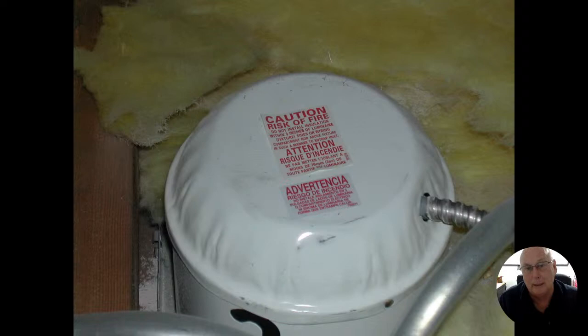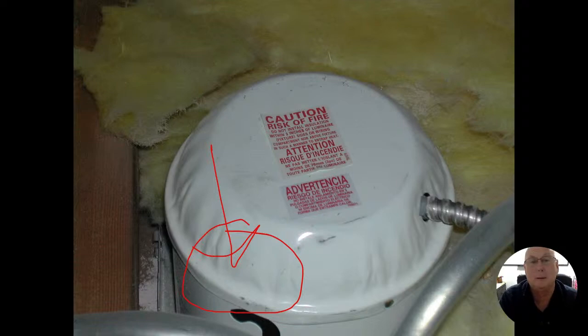If you have these can lights up in an attic or an unconditioned space, you're going to have a tremendous amount of heat loss coming up through there, because this opening down here at the bottom, I couldn't get down there, sorry, that opening at the bottom is clear through. You'll actually see light shining through there. Same thing where this pipe comes through. Once those bulbs start getting hot, heat just goes up into the attic. And once we start heating our attic, we're asking for a lot of other problems such as ice damming, moisture, everything else that's going up in there. Not to mention it can't dissipate the heat of these things, so we don't want the insulation touching it, all right? IC rated can lights are typically going to be silver or unpainted.